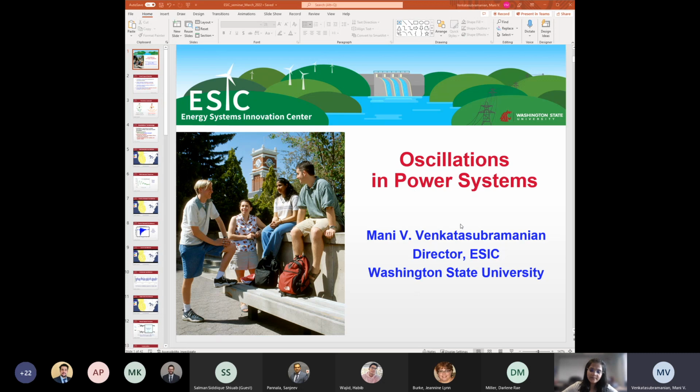Yeah, again, the mismatches were at various levels in the parameters of the generators and in the behavior of governors and exciters. Some of the limiters were not modeled or properly captured. The big realization was it's not just sufficient to have a generator model in the system, but it needs to be validated and verified. And since that time, NERC has introduced standards that explicitly stipulate this as a requirement for reliable system operation. Now, how we do this for renewables is still being debated because of the inherent complexities in modeling and analyzing renewables.